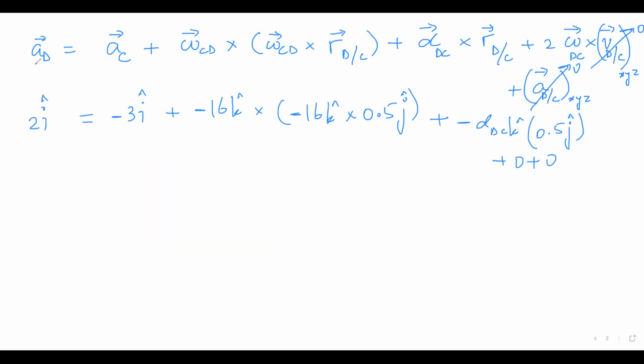So students should write 2 arrows like here. One will be the ADT vector, one will be the ADN vector. For ADT, you wrote 2i. What about ADN? For the point D, the normal acceleration will be downwards, right? So I will put minus ADN J, and here I will put 2 arrows. Please stop me if this is not clear.